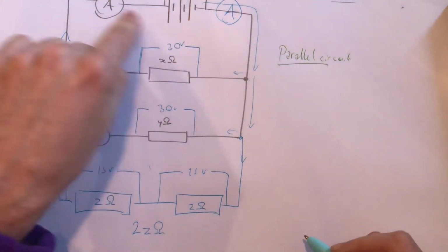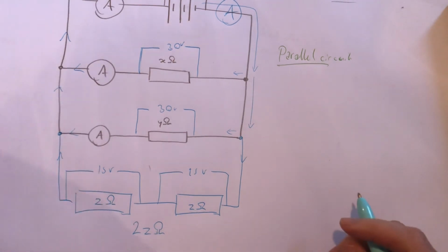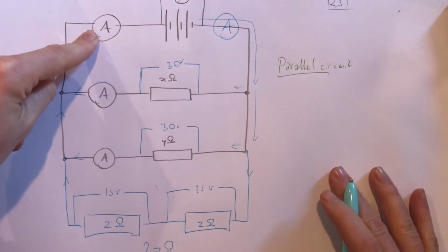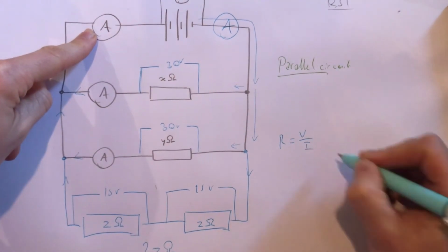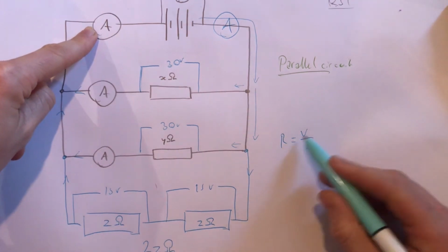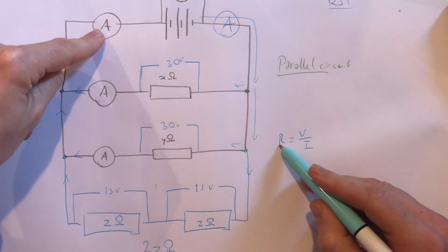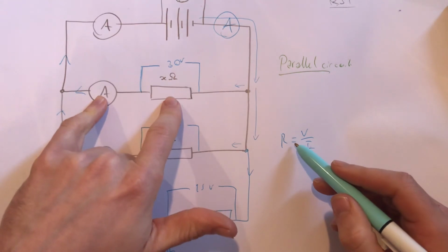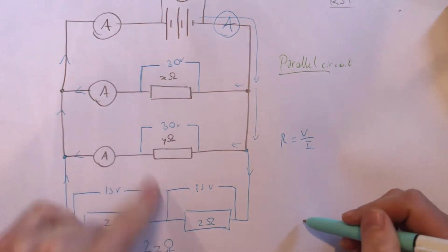Okay, and if we wanted to get the entire resistance for the whole network, actually it'd be fairly easy, because what we could do, for example, is read this current up here and then just do R equals V over I. So we would just solve with V and just read off this current. We would solve for R. What we could do then is also find the resistance of this by taking this and dividing by whatever reading for the current, and likewise here and so on.